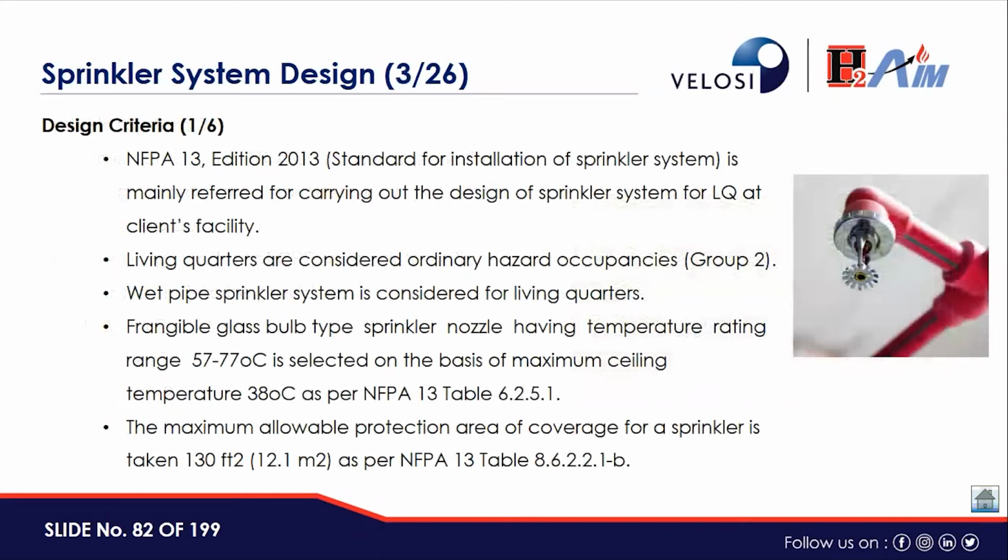So what was the design criteria? NFPA 13 edition 2013, which is a standard for installation of sprinkler systems, is mainly referred for carrying out the design of the sprinkler system for living quarters at this client facility. Living quarters are considered ordinary hazard occupancies, group 2. Then we considered a wet pipe sprinkler system for the living quarters.